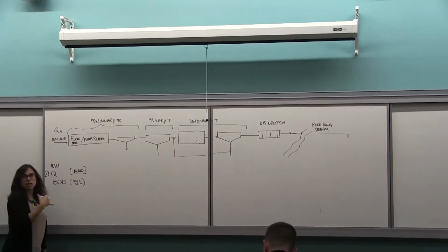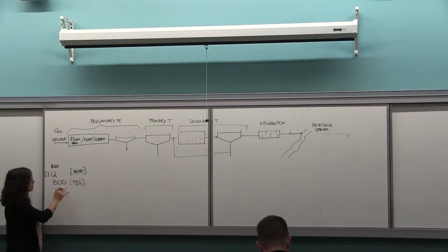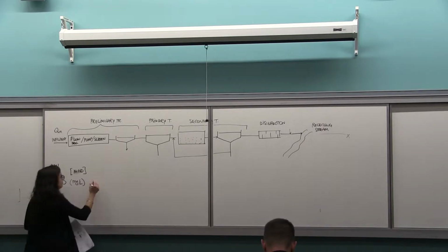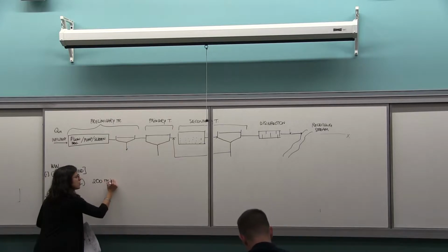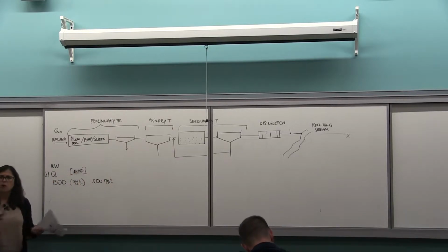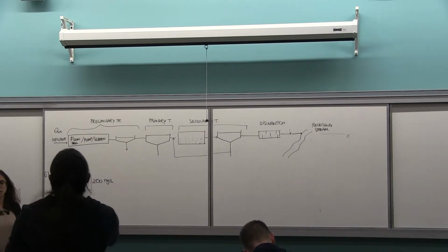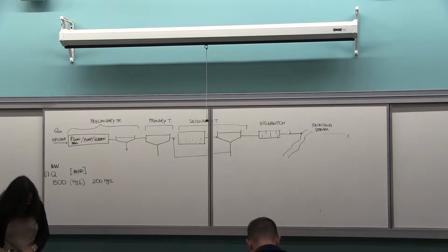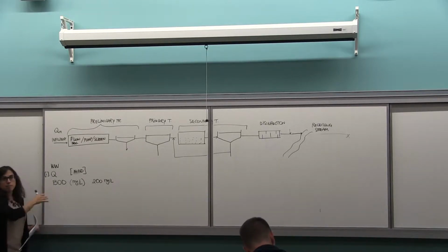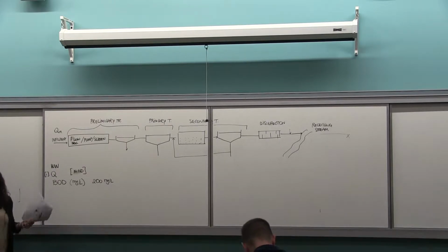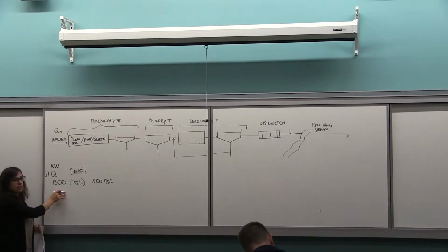Usually concentration depends on how many people this wastewater treatment plant serves. In terms of concentration, a typical BOD concentration is 200 for a medium strength wastewater, but it can go anywhere from 150 to 350 depending on the characteristics. So organic loading is one of the main pollutants. Together with the organic loading, BOD, biochemical oxygen demand, we'll talk a little bit more.